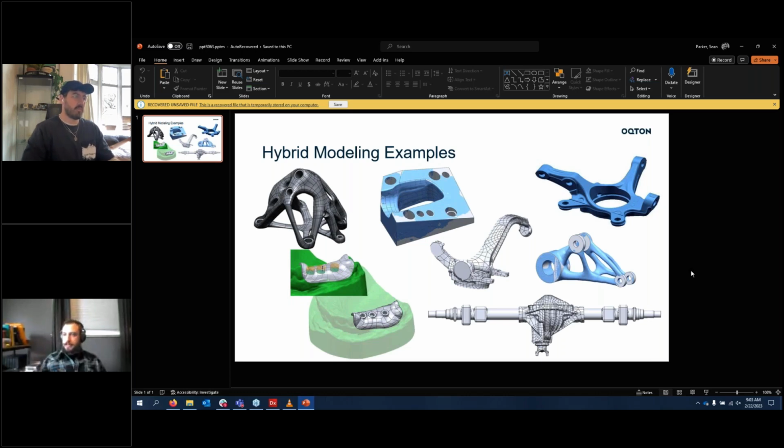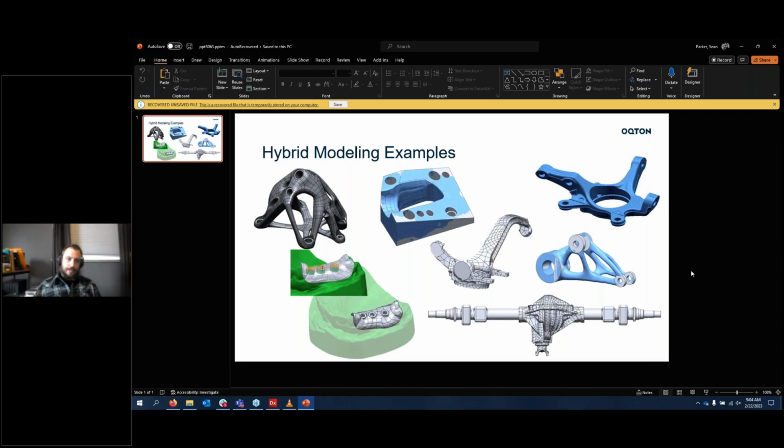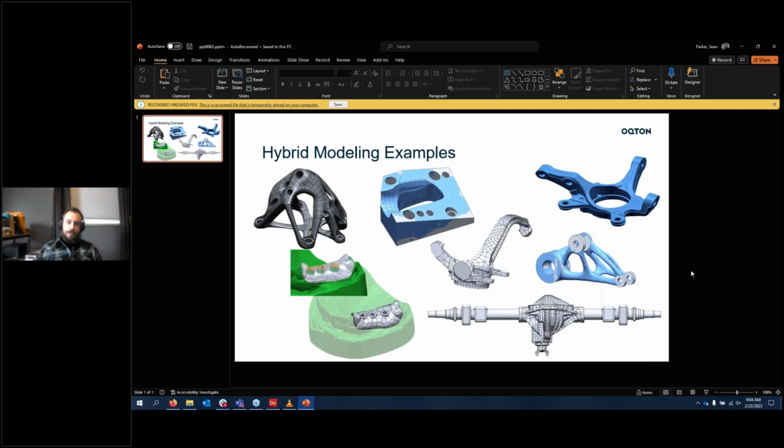in Design X. So what the exact surfacing, selective surfacing option does for us is it allows us to not use the auto surfacing command on the entire mesh, essentially. Basically, choosing what areas of the scan to ignore.